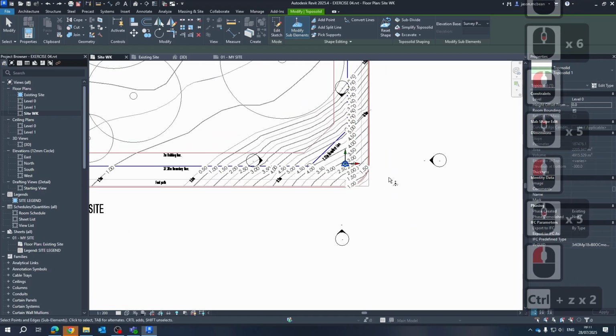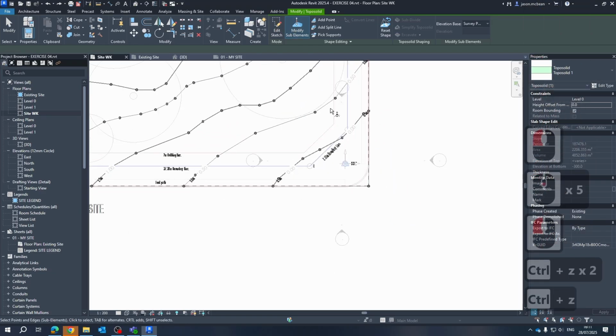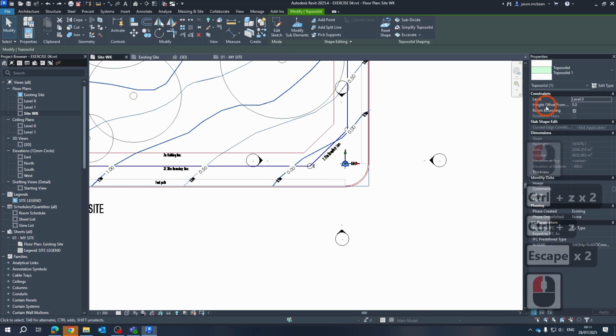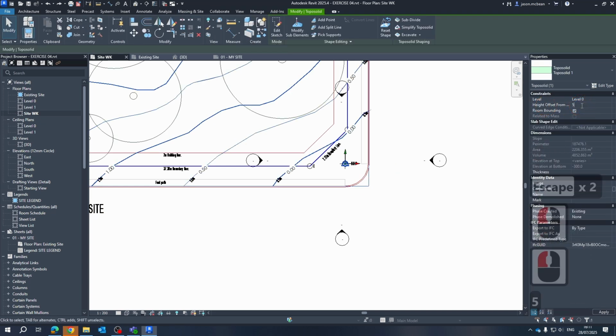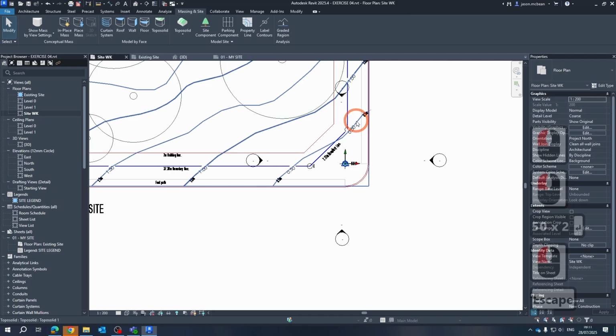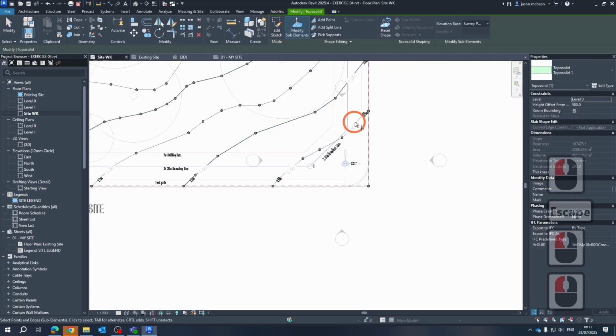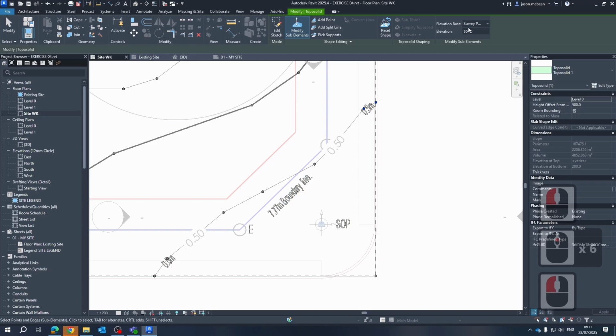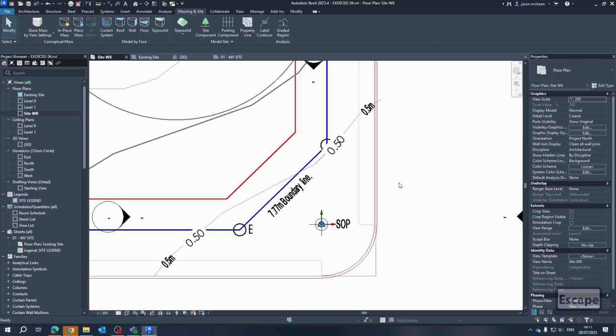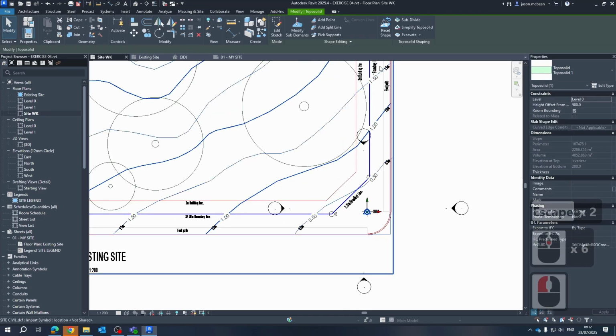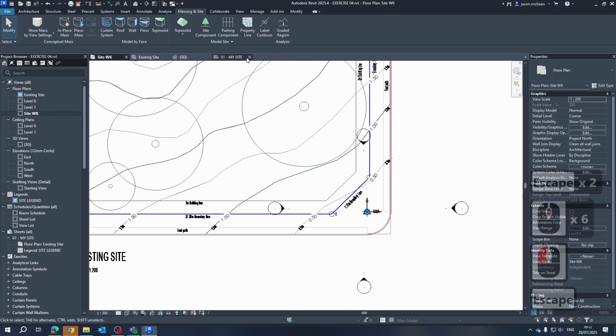Okay, I'm just going to undo that for now. Undo. I'll leave the offset as it is because it will give us the correct information. So 500. You'll see that it does adjust the contours, and if we edit the topographies, if we modify a point and I select this information, you can see that the elevation is correct. But typically you shouldn't be offsetting this at all. So that is a bit of a concern with this new version.